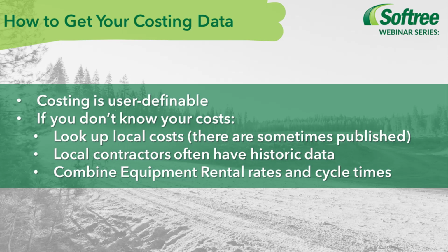And if you're looking for a more universal solution or being able to derive those costs yourself, you may be able to look up rental rates for equipment in your area and combine that with cycle times to come up with your own per cubic meter or per cubic yard costs.